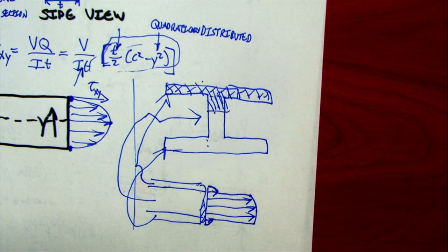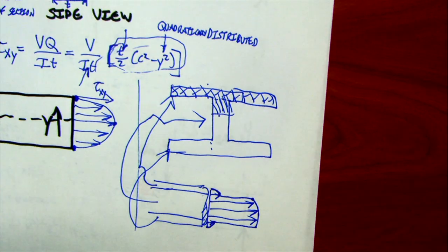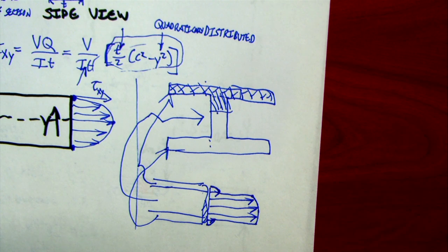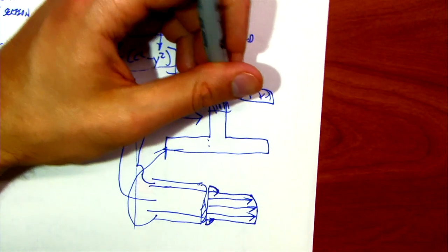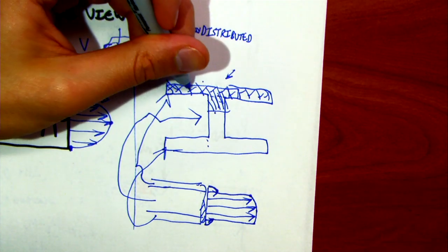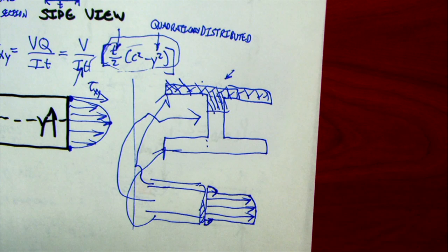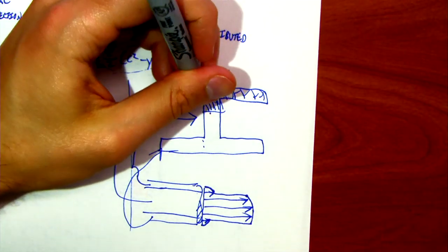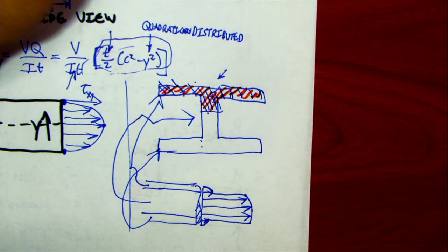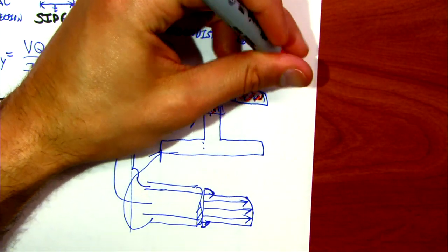And if we wanted to, we could write out the equations for that and get a value for Q that corresponds to the centroid of this cross section, this different color, this orange section, because we'll call it Q equals A y bar, right?